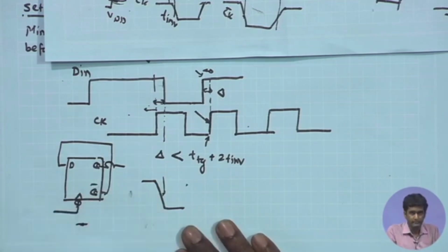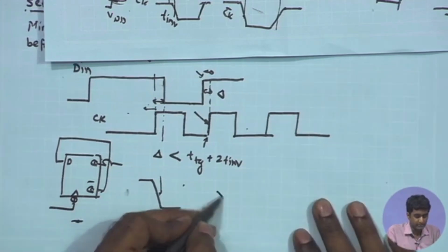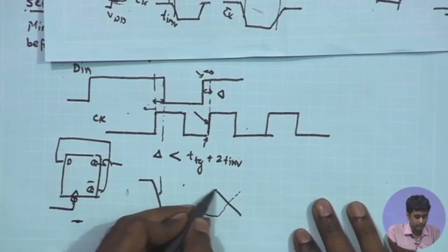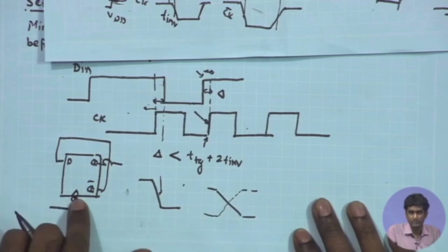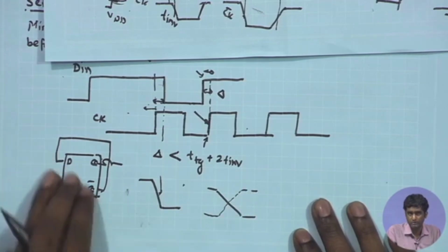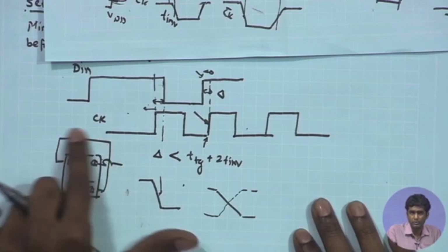What about the hold time? Is it a concern? If you have bad transition times for the clock and clock bar, which are going into this flip flop. Of course, I have shown one clock, but ultimately you have to produce both the clock and clock bar, which are going to control the TGs in this flip flop, and you are connecting the Q bar to the D.